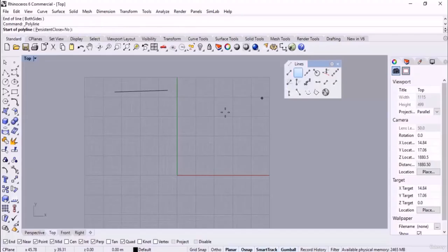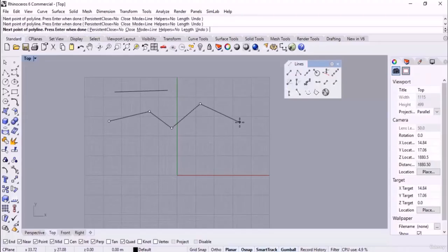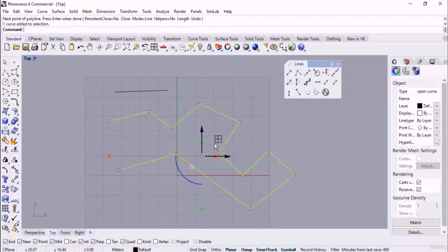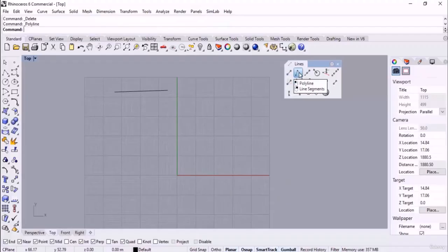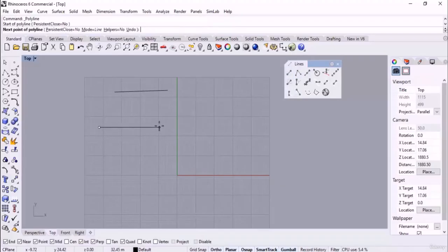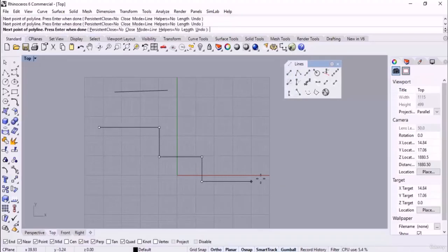But the tool that we were using was polyline, that it allows us to sketch multiple lines sequentially, so we can keep on sketching lines until you press enter or right click, and the sketching command will be finished or cancelled. But if you are using polyline, like this way as you can see on the scene, if you press down escape button, the whole sketching will be cancelled and deleted, and you can't turn them back by undo, since the changes weren't saved yet.